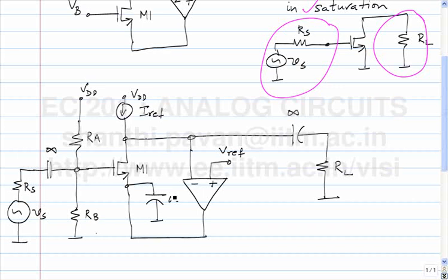So, if you put a capacitor across a voltage source, what happens? If you put anything across an ideal voltage source, what happens? That element has no effect on the voltage at all. So this circuit will merrily continue to do what it was doing earlier without the infinite capacitor.